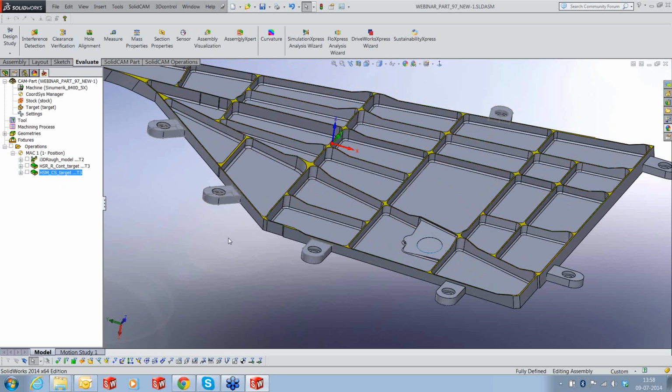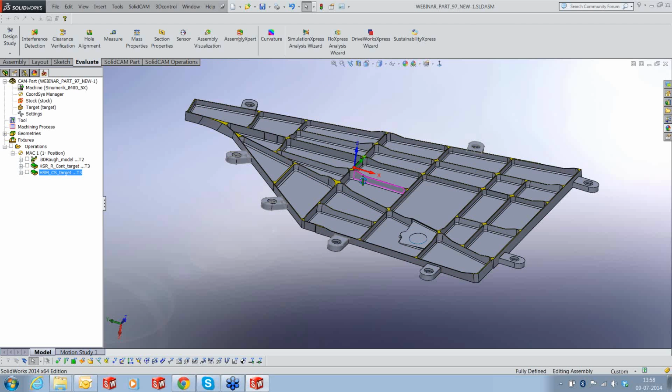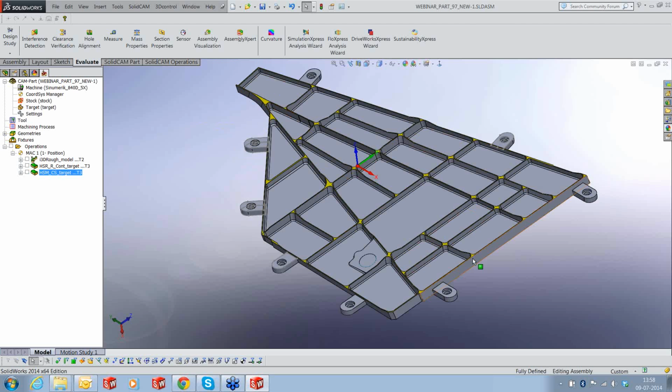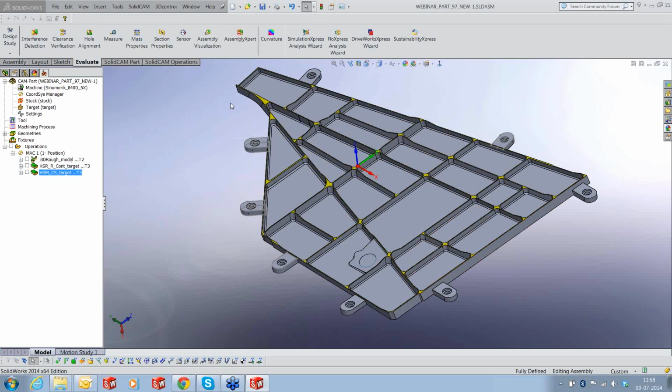Now what we have to do is, we have done with the ribs, we have done with the roughing of the outer edge. Now we will rough the inside. And again, I'm going to use iMachining 3D.